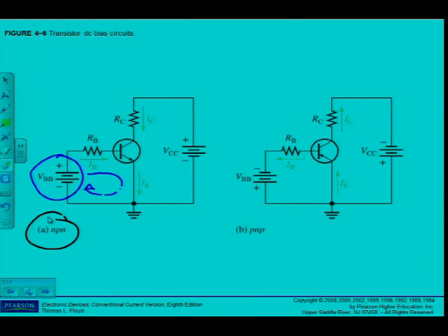Approximately, because remember, you've done the diode and you've seen in the lab that the voltage is not actually 0.7, that's an average that we take, but for all our calculations we will use this approximation. I have another supply which is called VCC, which will let the current flow in that direction for IC, and I can see that my base collector junction should now be reverse biased, and I have my forward reverse bias condition as I should have for a biased amplifier circuit.